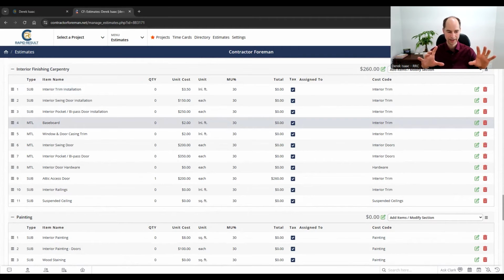If you've got certain saddle or sashes or whatever, a different design for the base of the windows, of course, you got to take that into account. But typically with rough budgeting, you're doing basic. And then if they ask for additional details, then you'd add those in. If you're working from plans and you can easily see that they've got a lot of detail on your trim, bump it up a little bit. You don't want to be negligent here, like we totally ignored the plans and just went with what we thought would be the lowest price possible, right? Go towards the plans, but don't spend a ton of time overthinking it.